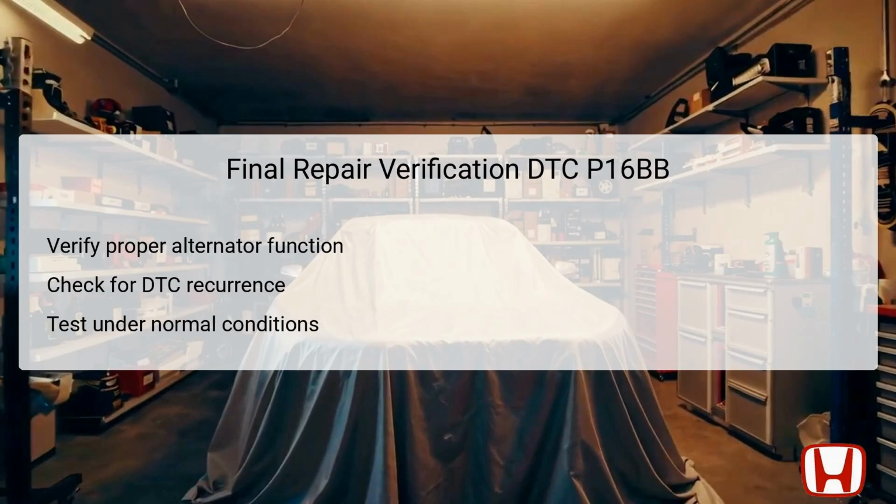This verification process includes checking the alternator's output to ensure that it effectively supplies the necessary voltage to the vehicle's electrical systems. Additionally, using the HDS, the technician should confirm that the DTC P16BB does not reappear, indicating that the previous problems have been adequately rectified.